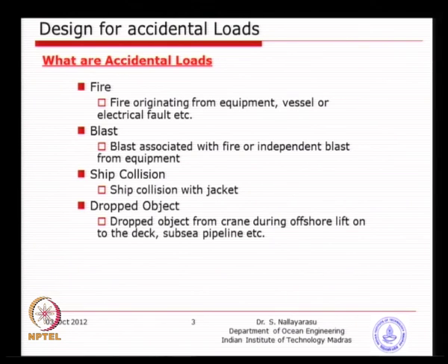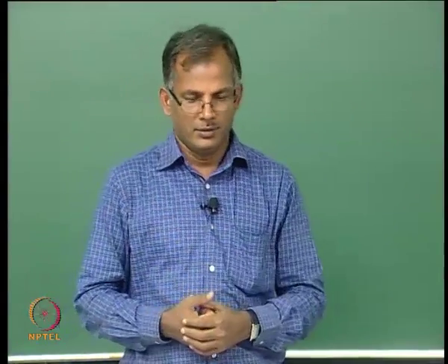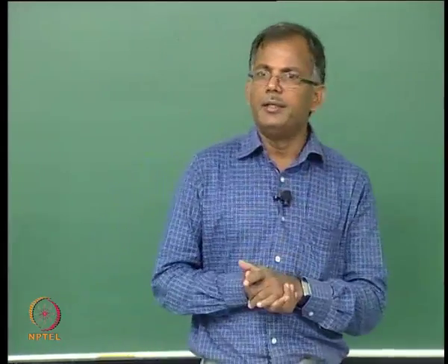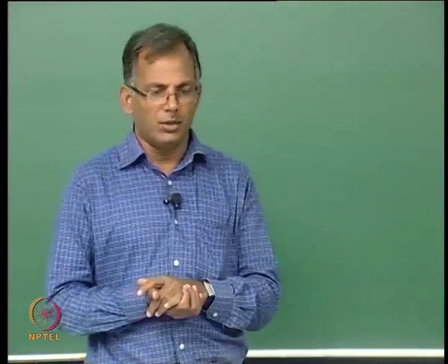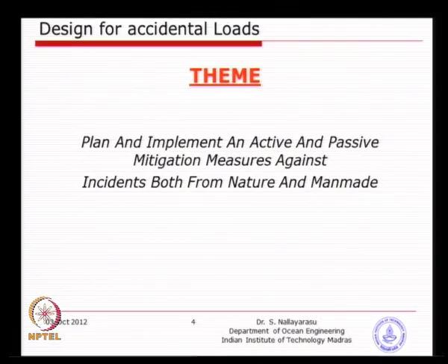You are going to have an impact energy and you are going to look at what type of damage happened, how much energy is absorbed while the structure is deforming, whether it is a ship impact or a dropped object. The idea behind designing against these accidental loads is that implementing active and passive mitigation measures is very important.